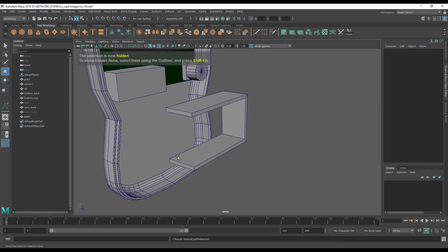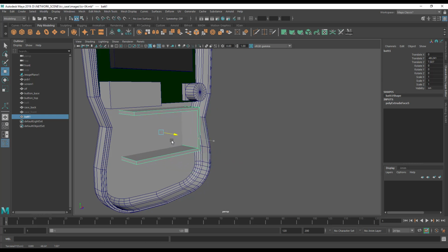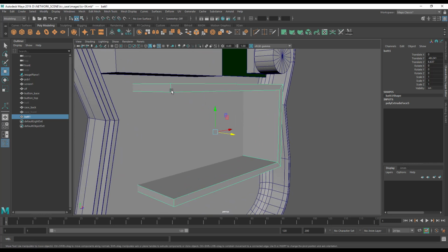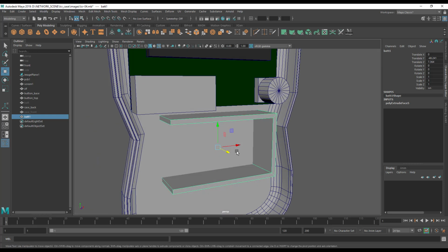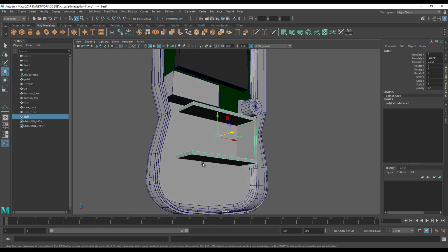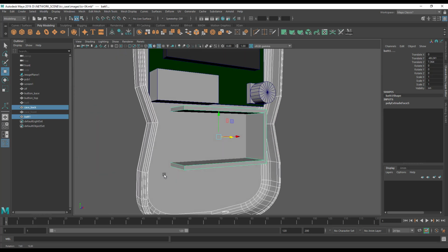So if I just make something clear here, if I'm 3D printing something, unlike Maya where you'd normally try and merge the mesh together properly, if I just whack this in here so it bisects other geometry, a 3D printer will see this as all one object. It will not care if you've grouped it, merged it, joined the vertex together. If one object is intersected with another, it will just count it as one object. So if I want to do our basic battery holder like this, when this comes to 3D print, when Slicer gets hold of it, it will just see this whole thing and this whole thing as one object.